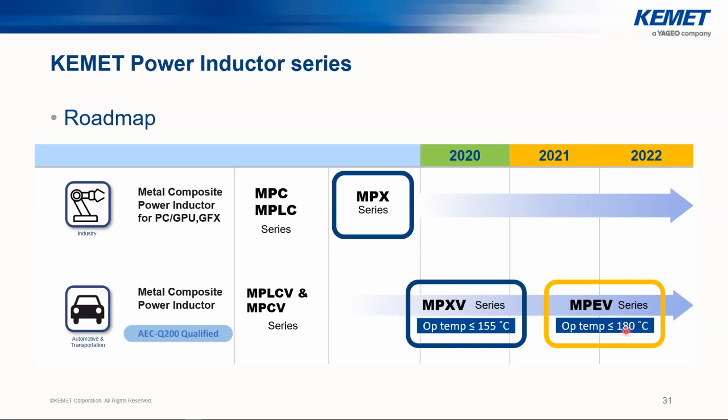That doesn't mean that this is the maximum temperature of your application. This is the maximum temperature of the inductor. So self-heating plus ambient temperature.